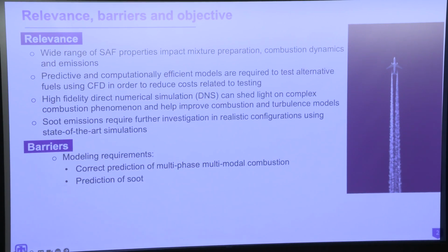So it may not just be non-premixed combustion or premixed combustion, but it could be a mix of partially premixed and non-premixed everywhere. So the models would have to be able to predict that kind of behavior when you push into these rate limiting operating conditions. And also we need soot models that can be incorporated in CFD calculations.